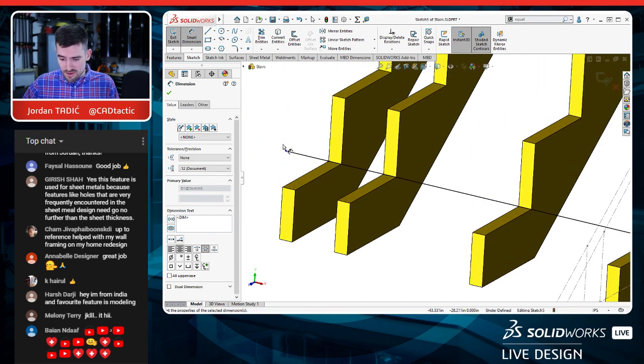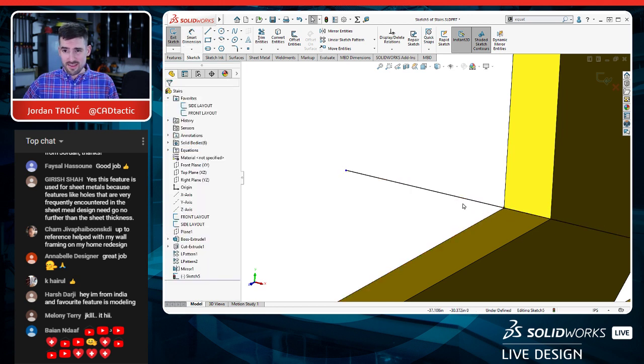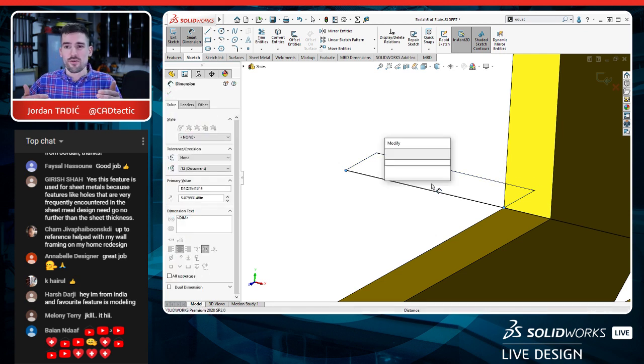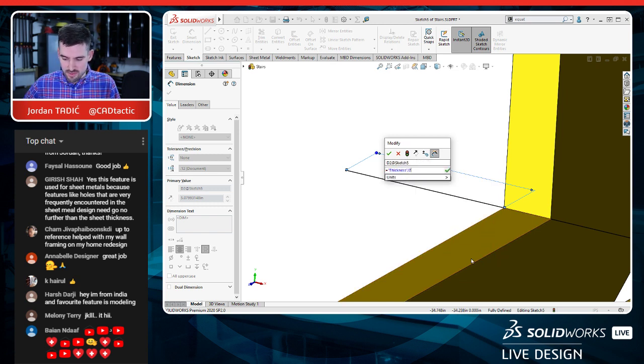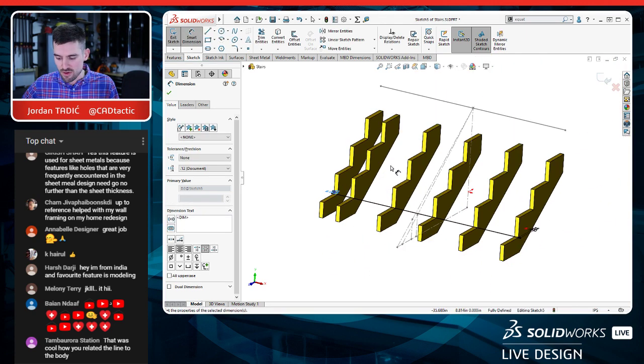But if you're in a country where 1.5 inches isn't the standard width of the board, you can download my model and change just the thickness value, and you'll be able to update everything all at once, just with one value, including this overhang. So if you change this to 1 inch or something like that, it will change to a 1/2 inch overhang. So let's do that again. This equals the thickness divided by 2. So you can type math right into the modify dialog box as you go. The key is you just have to add that equal sign at the beginning.